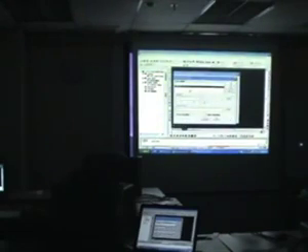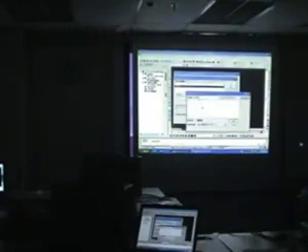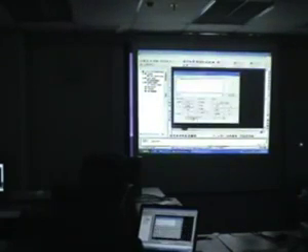So we're kind of cheating here. We've got x and y, and string, which when we import this later, we're going to specify as z instead. And of course, you notice OK cannot be selected, so we're going to output to an XYZ file. It's called points.txt. Click OK and click execute.